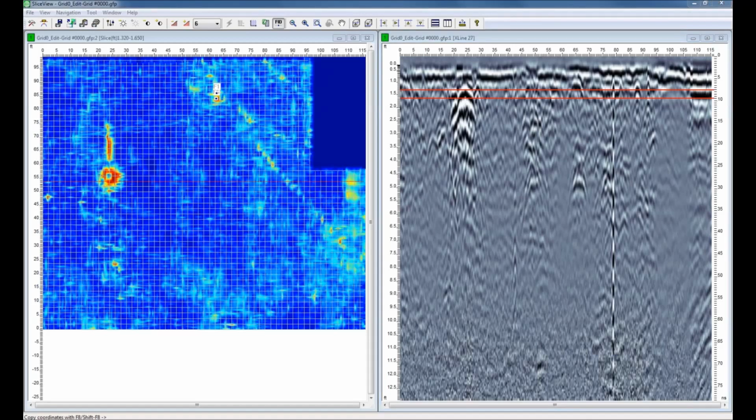Now, if I want to know approximately how big that feature is, I can click on the Measure tool. Up here, you can see a little ruler. I can click on the button, and click and drag across that feature to measure its distance. In the bottom left corner, it'll give me a distance. So this thing is somewhere around 7 feet in diameter or so. Obviously that's going to be interesting information when we're trying to do our interpretation of what this